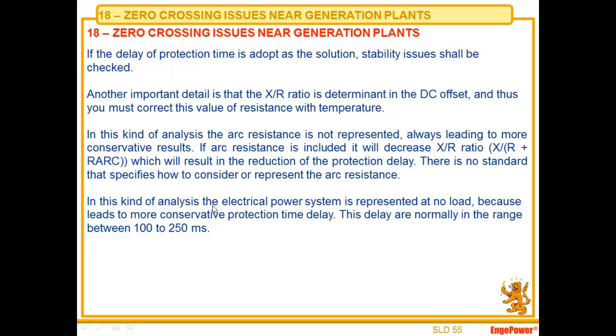In this kind of analysis, the electrical power system is represented at no load because it leads to a more conservative protection time delay. These delays are normally in the range of 100 to 250 milliseconds.